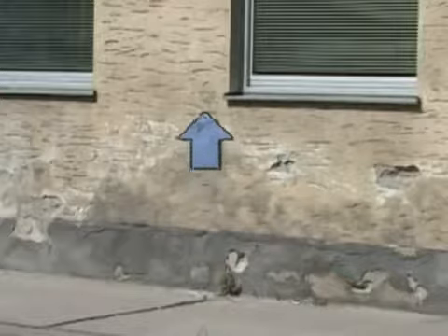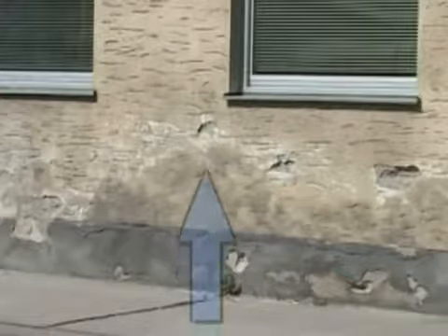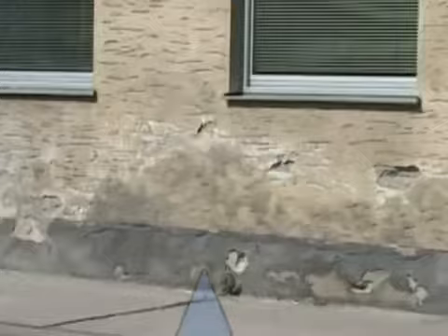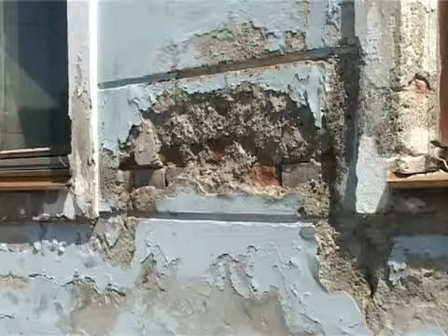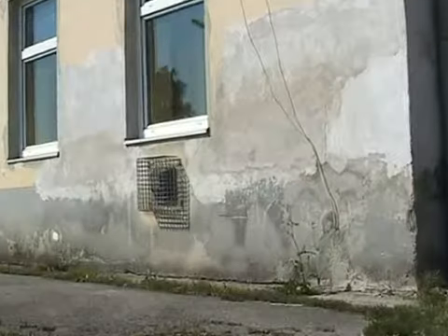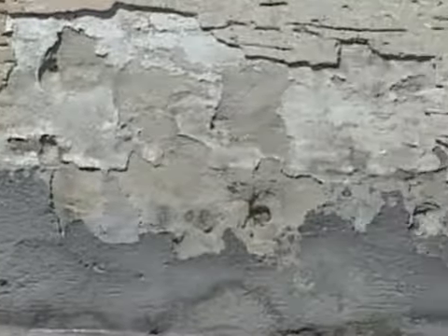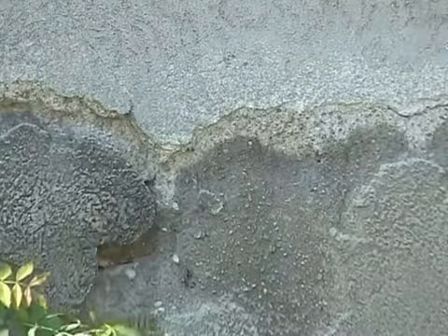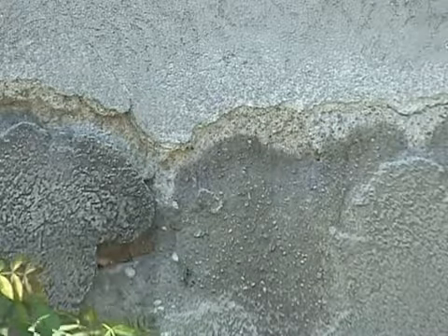In the graphic diagram you see how ground moisture is rising. It's a nearly invisible phenomenon. It becomes visible in higher portions of the wall due to the damaged plaster. The results are damage of paint, water stains, salt efflorescence and plaster flaking on the facade of the house. By the interaction of complex chemical and physical forces acting on this masonry, it will be slowly but surely destroyed.